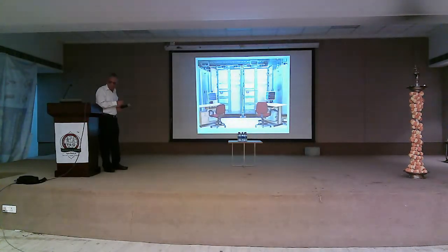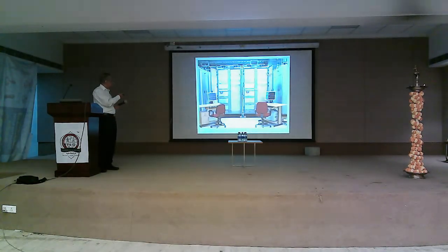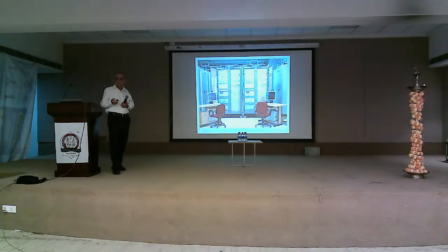And this is the actual system which was manufactured in the electronics workshop and integrated under testing at the time. So you see this is the processor card image. Both are represented here. This is the bus master, and here is the bus. The bus gets extended to a digital input output port with analog input output port. There is a signal conditioning port which provides the transformer isolation for inputs.